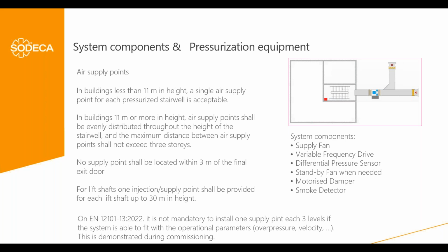In part 13, we don't have these requirements, because at the end of the day, the responsibility for the system is in the hands of the system installer, so it gives more responsibility to the installer. No matter the number of points installed in the system, if when we make the test we pass it, we achieve the 30 pascals in all the levels, we achieve the 1 meter per second in all the levels, and we achieve the reaction times, then no matter the number of supply points and where they are placed, it is acceptable. This is a problem for the designers, because when we design,